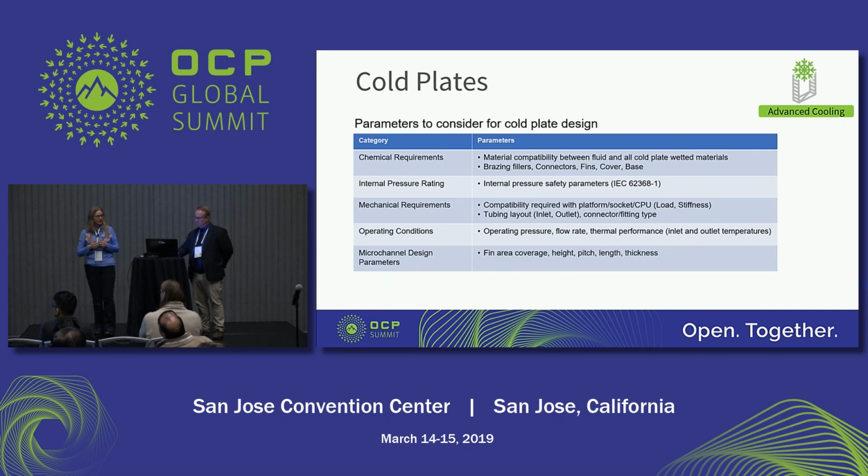They also need to meet the internal pressure ratings, right, of the IEC standards, of either 2 times or 3 times the pressure. You need to meet the mechanical requirements. So if you're putting in your cold plate and loading it, you need to be able to take that load and have enough stiffness and meet those requirements. You need to fit the cooling loop inside of the IT equipment.